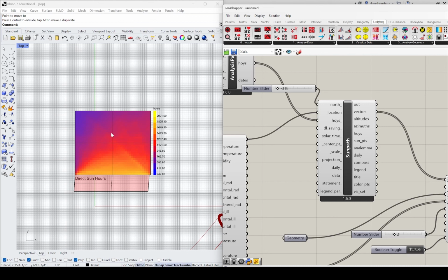So this is just a horizontal one, sticking out from the building horizontally. If you're facing west and east, vertical louvers tend to be the best. So you can look at vertical ones, or you can look at some combination. How deep do you want them? What's the spacing on them, and see the different things, right? So this is just one way to look at daylighting.